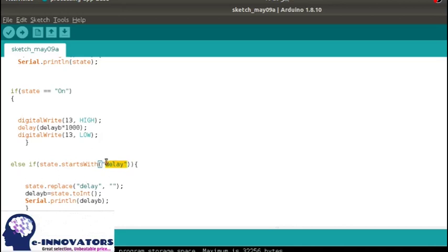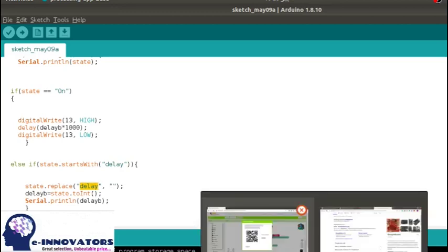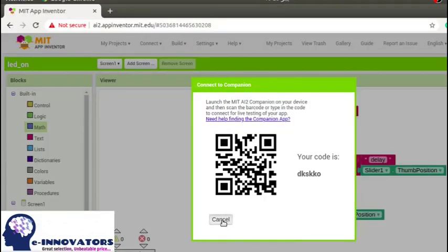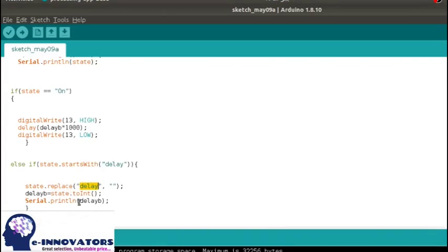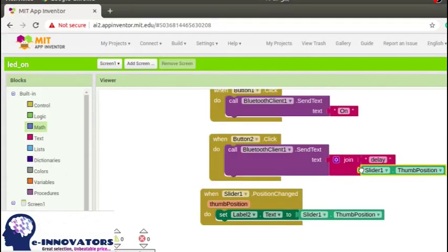Here we can see the importance of join method. If we remove the delay, we only get thumb position, which can also be a floating point. To change it into integer, go to the math. Select round and drag it to the block, which rounds off the decimal value, or we can say changes float into integer. Finally compile and run the code of Arduino UNO.